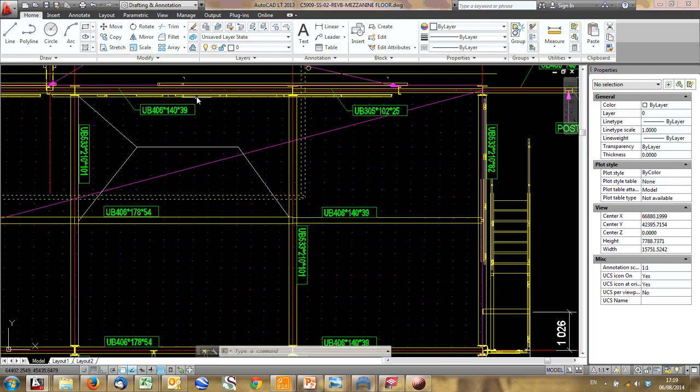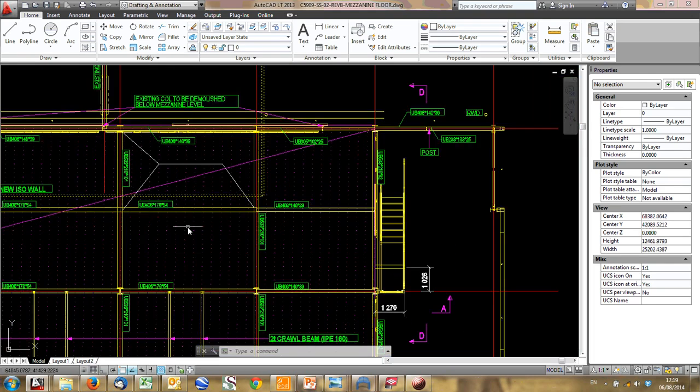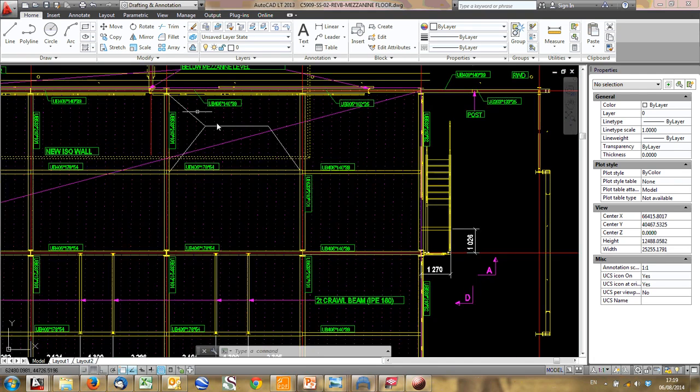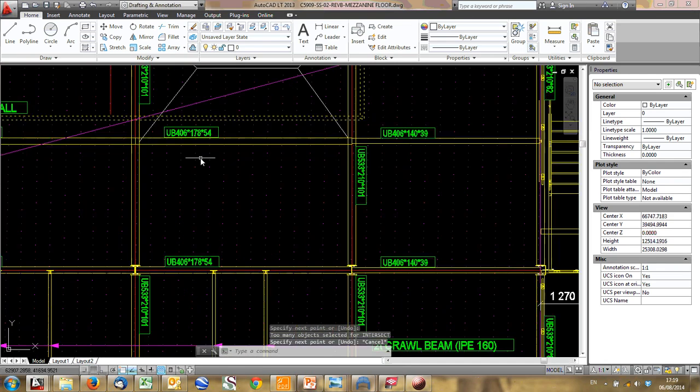So this is fixed-pinned because this is continuous this way, this concrete slab we're looking at. So 55-60% of the load will go here, whereas 40-45% of the load will go there. All right, and you can then do the same thing. This just highlights how much load goes on each of these. But now, once again, we analyze our beam, simply supported,